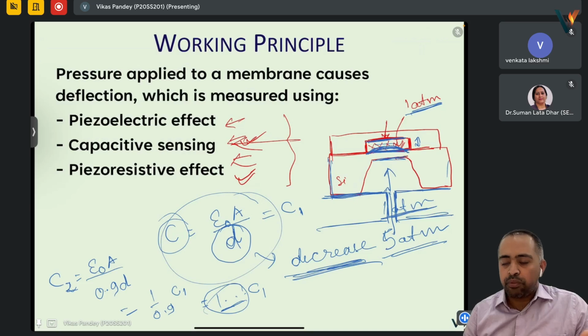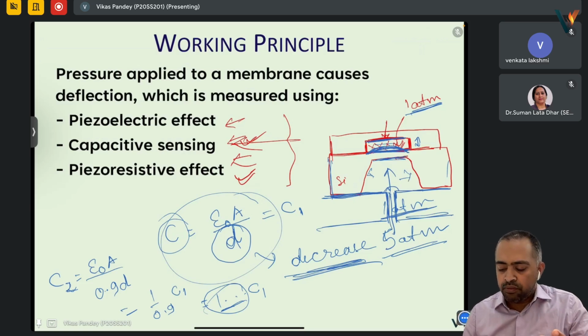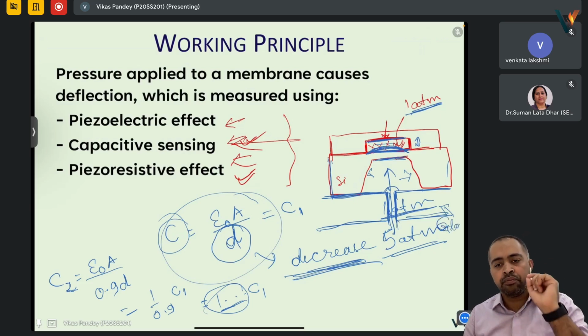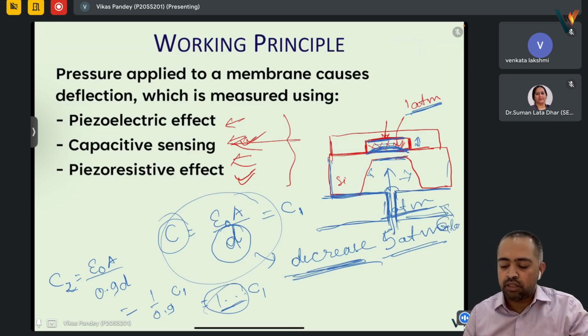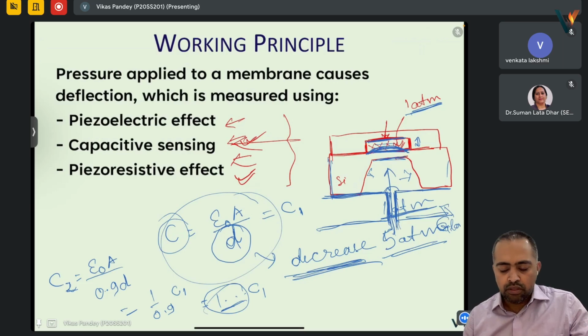We will not see non-uniform disturbances. If it is open, it can have different pressures over different parts of the sensor. So to make it more uniform, a simple tube-like hole is kept. This is generally glass, so it is covered with glass with a hole or tubular structure. Again, this etching is done just like we did bulk micromachining of silicon. We can do similar to that for the glass.